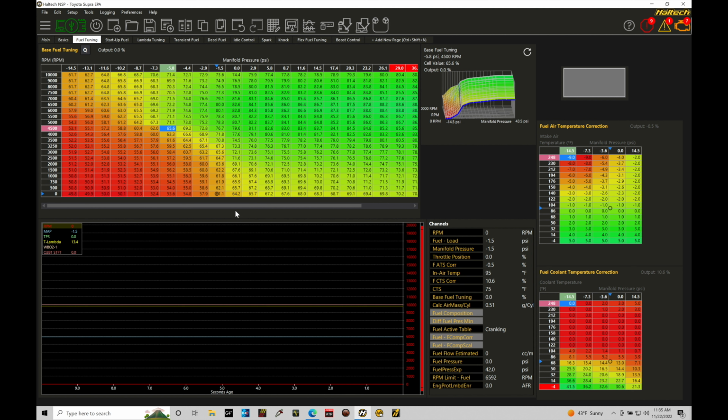So the first thing I want to do here is talk about some things we want to turn on and make sure are configured so we can work with something like fuel pressure integration or short pulse width integration. We also need to account for the type of fuel system that we have. Do we have a vacuum referenced fuel pressure regulator that'll vary our fuel pressure according to our manifold pressure, or do we have a fixed fuel pressure system that's going to be known typically as a returnless style fuel system where we don't have a return line, and there's a mechanical regulator that's keeping the fuel pressure fixed at a certain amount as the fuel's coming from our fuel pump going into the feed line. So let's take a look here at configuring some of these details and understanding what's going on here.